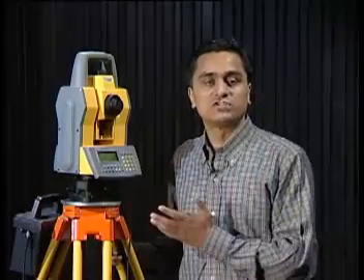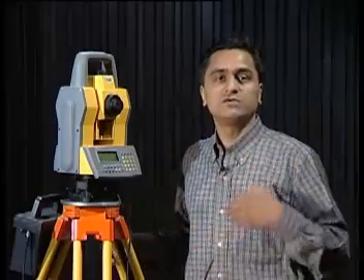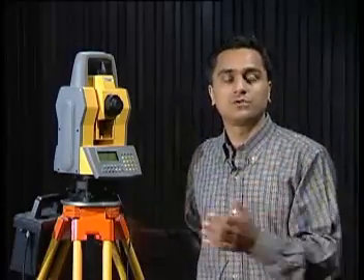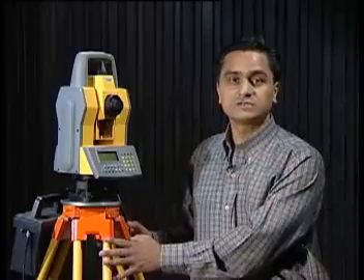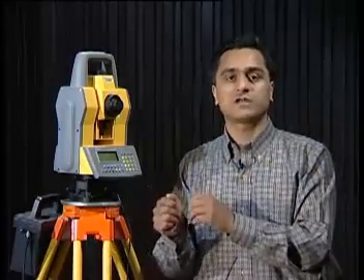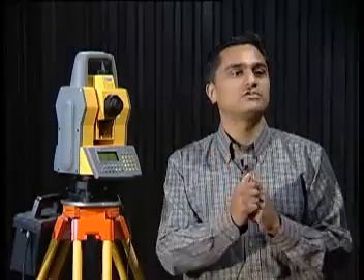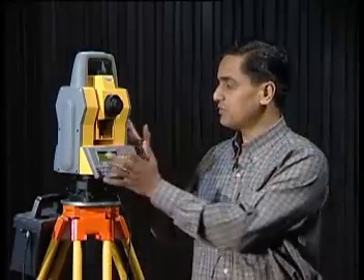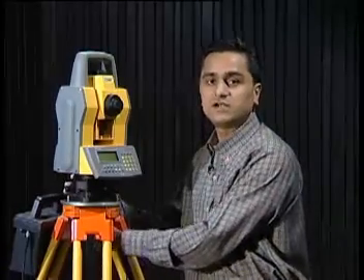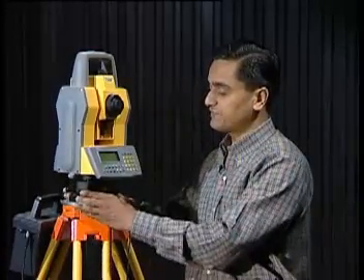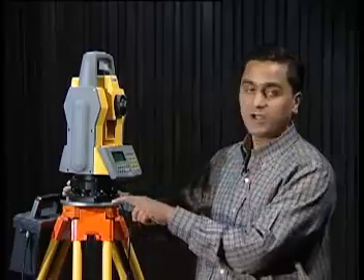Okay, here is the total station. As you can see, in the case of the theodolite, we go to the ground and set it over the tripod, and here is also a tripod with us. So we first set the tripod, level the tripod, the steps which we talked about in the theodolite, same thing here. Then you put the total station on top of the tripod, and now I can center it accurately by shifting the total station on the tripod head.